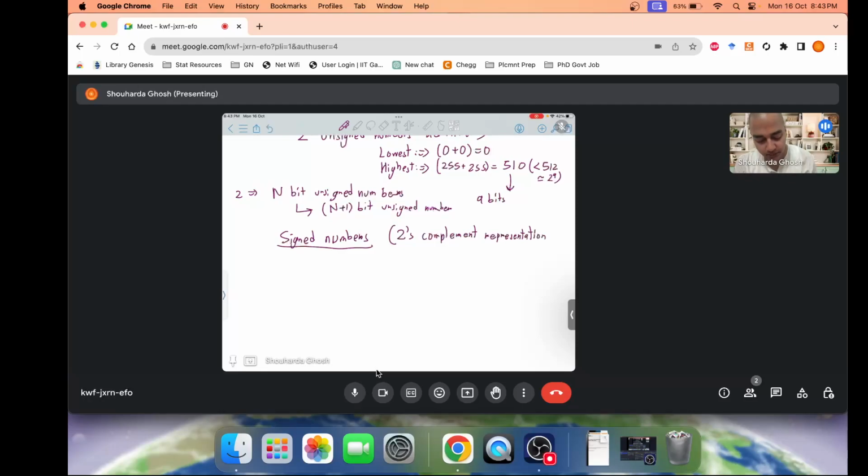And actually 2's complement representation is chosen because it is hardware friendly. If you look at other forms of representation, their corresponding additions or multiplications will require extra logic circuits for decoding whether it is positive.